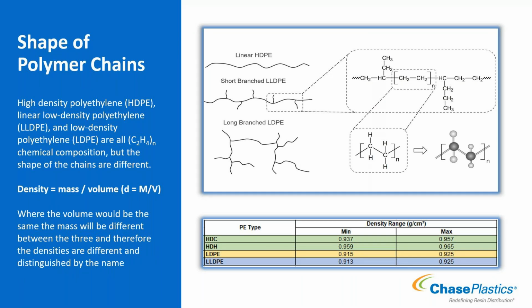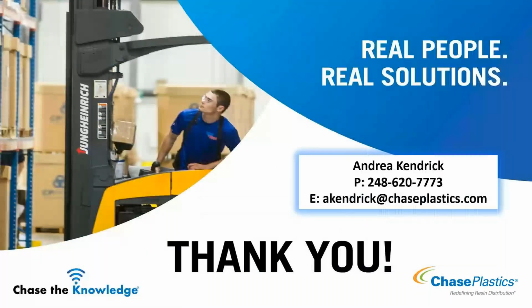Can you overview polycarbonate copolymers in regard to crystalline and amorphous classification? Polycarbonate copolymers, is that what was asked? Correct. So most of the copolymers are going to be amorphous still. And so it's polycarbonate on the backbone, which is going to be your amorphous. And then depending on the copolymer type, you add different stuff into it.